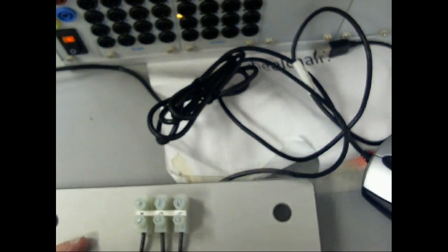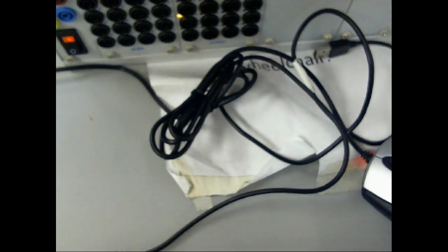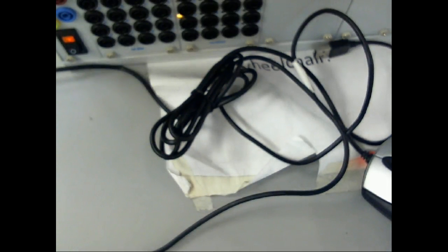We have programmable timers. Well, we have different types of timers. A programmable timer is you tell it what type of timer it is, whether it's an off delay or an on delay, or retentive or non-retentive, or a cycle timer, or what other timers that we have. I didn't show you a cycle timer, a mechanical cycle timer.